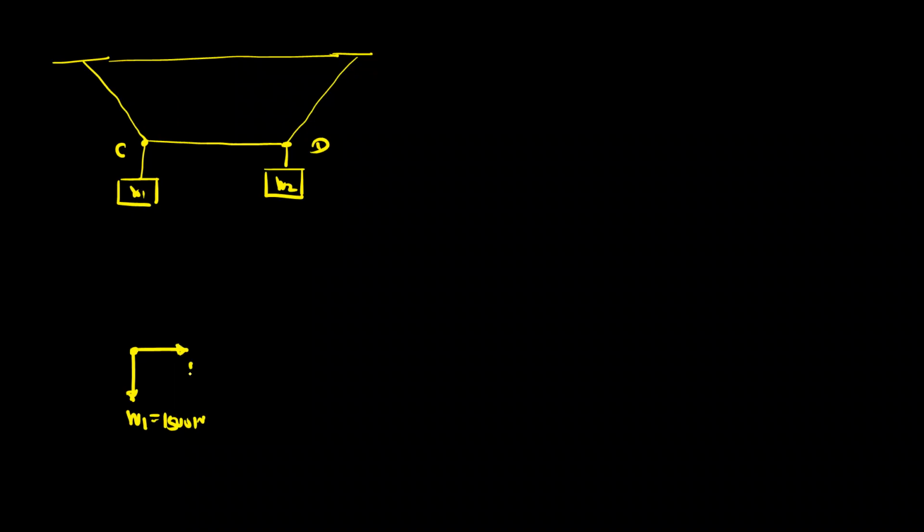This is the tension in the cable CD, and this is the tension AC. This angle is alpha, so alpha is equal to 28.96. You can check this answer by using the tan inverse formula. Now you can resolve this force, the tension AC, and use the conditions of equilibrium.